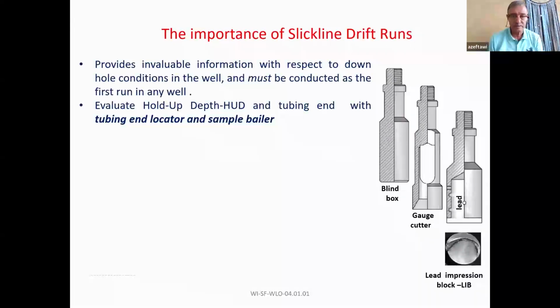Second question: how do we identify and differentiate stuffing box packing material for standard service and sour service by visual inspection? Never depend on visual inspection. You have to have the certificate which tells you this specific packing is suitable for one, two, and three.